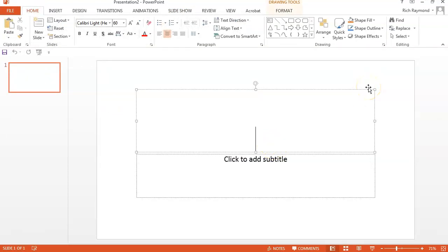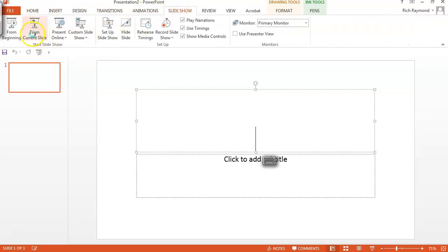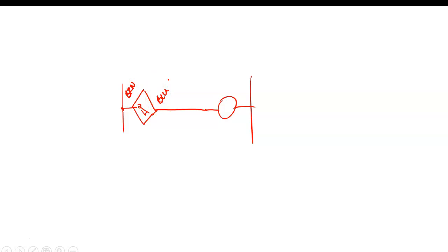So we have 2-wire sensors that we played around with this semester, and a 2-wire sensor powers up through the load, right? You understand that? That was our inductive sensor, and here we had 2 wires, and then we had different variations. And what were the colors? Brown and blue. And it powered up through the load, right? You understand that? Then we have a 3-wire sensor.